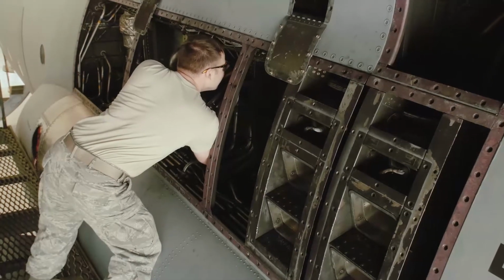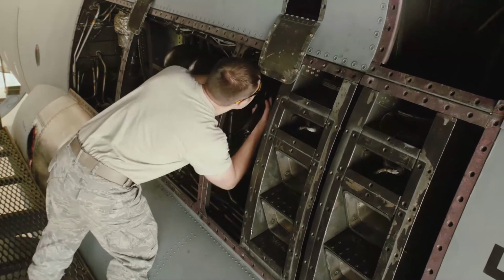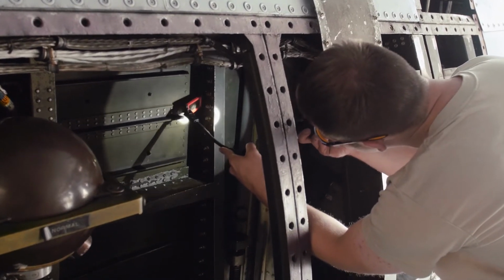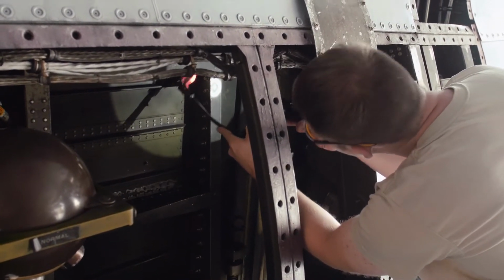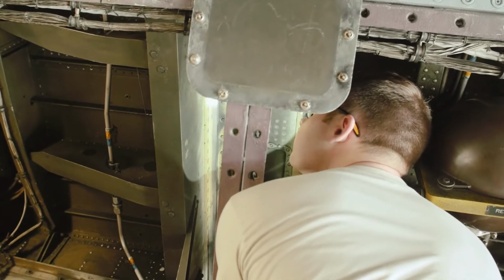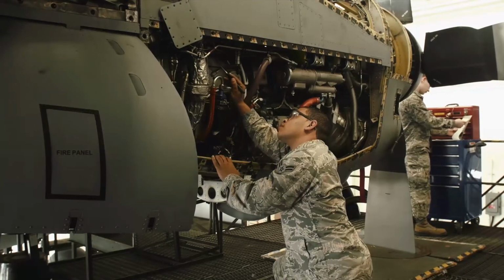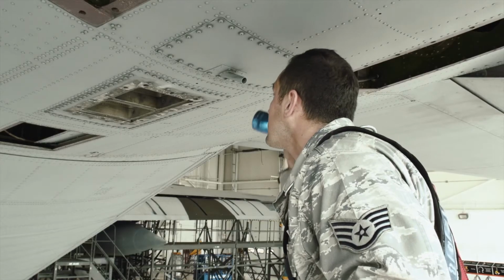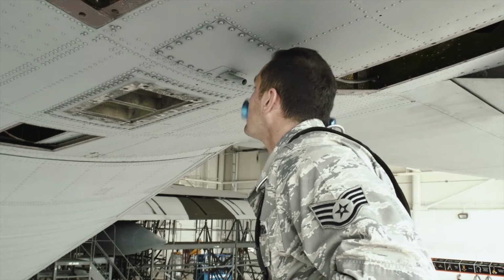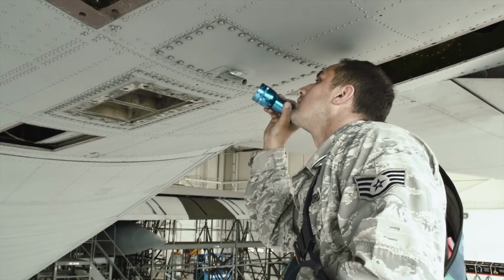System engineers are responsible for designing structures and components so that corrosion can be reduced, eliminated, or controlled. They try to anticipate where corrosion cells can develop and design the structure or component to eliminate at least one element of a corrosion cell. Or they make changes to the design to reduce the potential for cells to develop if it's impossible to completely eliminate them. For example, a steel fastener or cathode in direct contact with an aluminum skin or anode can create a corrosion cell that causes the aluminum to corrode if an electrolyte is present.